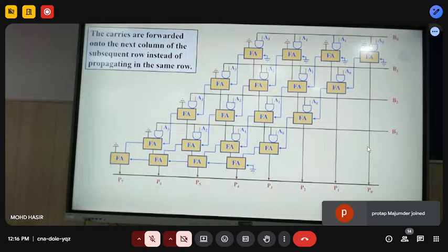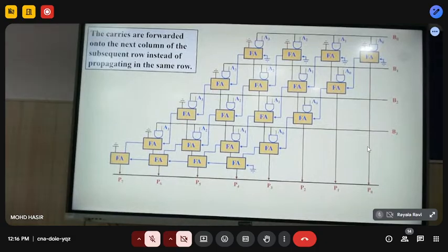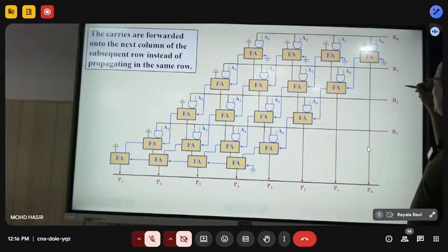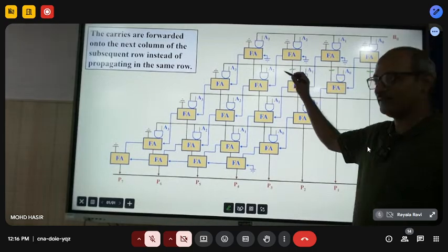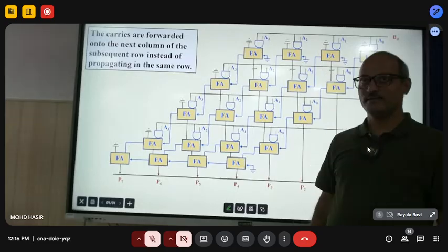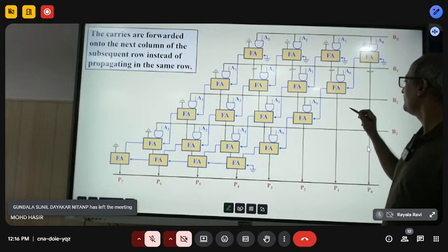Now where is the critical path? Again from LSB to MSB. Okay. So now I'll add the concept of pipeline architecture. So can we pipeline this? Yes. So where do I insert a pipeline so that it becomes optimal usage of the pipeline? See, one solution which is coming up is what is suggested here, right? At this place, at this place. Is it? Right. Then the other is to write here, right? Where?